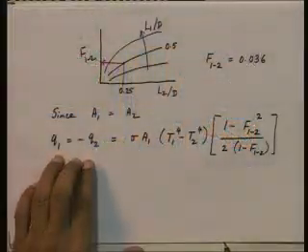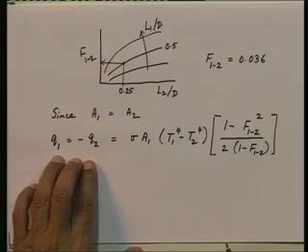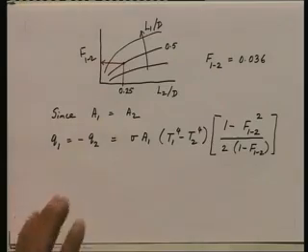Now, I have not mentioned it earlier, but note q 1 is equal to minus q 2, it has to be, all right. Why? Because there are 3 surfaces making up the enclosure. In a steady state, Q1 plus Q2 plus Q3 must be equal to 0. The first law of thermodynamics requires that, right. Net rate at which heat enters through all the three faces must be equal to 0. Q3 is equal to 0 in this case, therefore, Q1 must be equal to minus Q2.